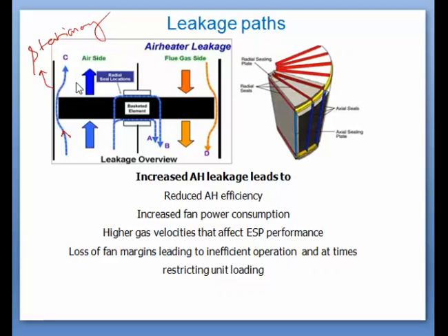So what happens with increased air heater leakages? The first thing is that it reduces the air heater's efficiency. It will increase the fan power consumption to supply the same amount of air. Some portion is lost because of the leakage, so the fan has to work more.